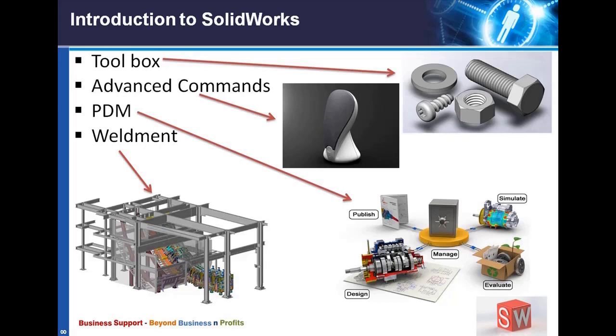This structural design fabrication assemblies, definitely you can do it using SolidWorks in a user-friendly way. If you look into these types of assemblies, the first primary requirement is we need the information about the cut list, that is, when I create the whole design, how many structural members I will use here, what is the length for the individual members, and all this you can achieve as simple as possible in SolidWorks.